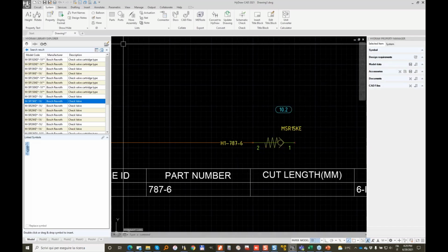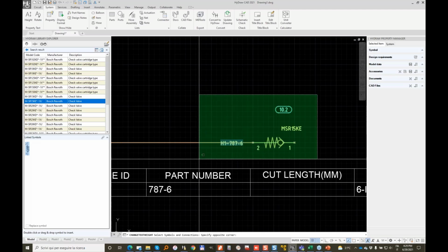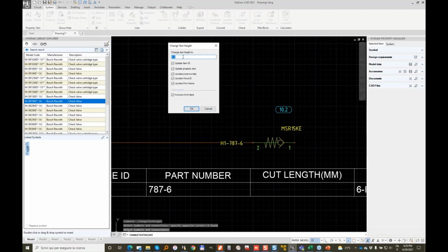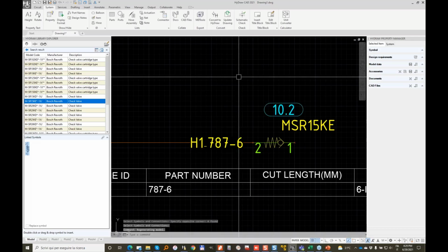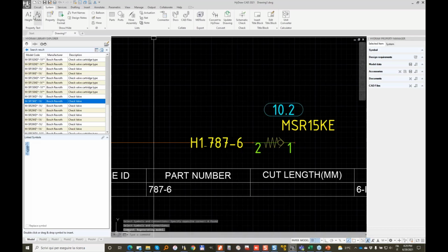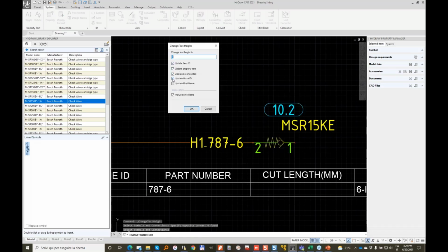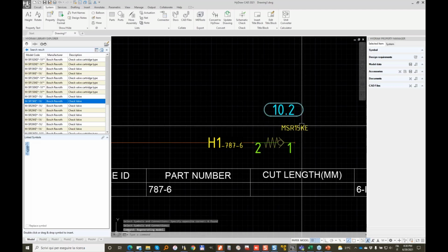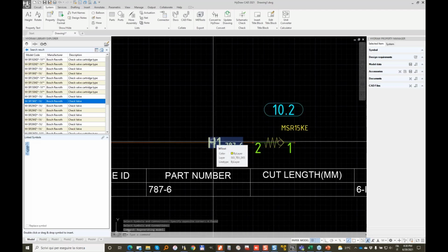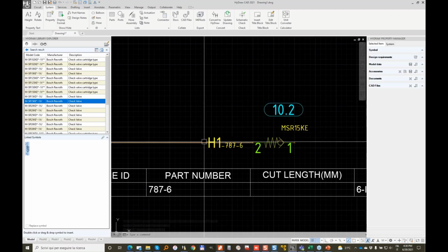So if we do the same height, then it will be easier because we just say 4, and that will have a different approach. So here you can control what you want to control, the text height for items. So we want only the item property text to 2 mm, and that is changing only the property text, keeping the line ID larger. That's it.